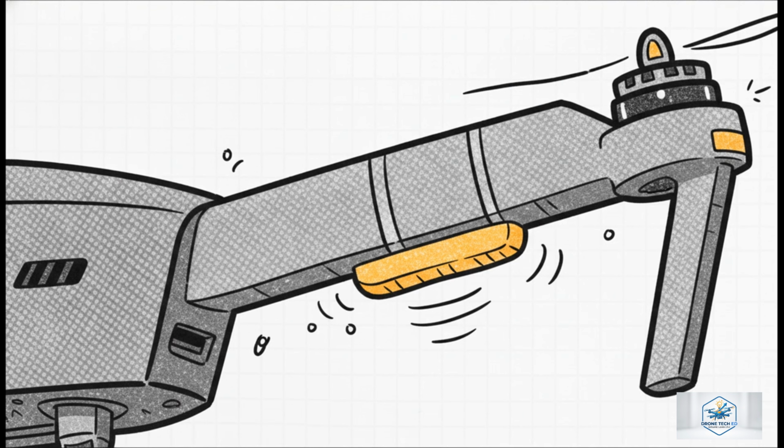To support all these intense aerodynamic forces, the physical construction has to be absolutely perfect. Modern professional drones aren't just using standard plastic. They use CNC precision-cut 3K twill-weave carbon fiber. We choose this specific material because it yields a massive 30% weight reduction compared to aluminum, while offering extreme high-G impact resistance. But there's a problem.